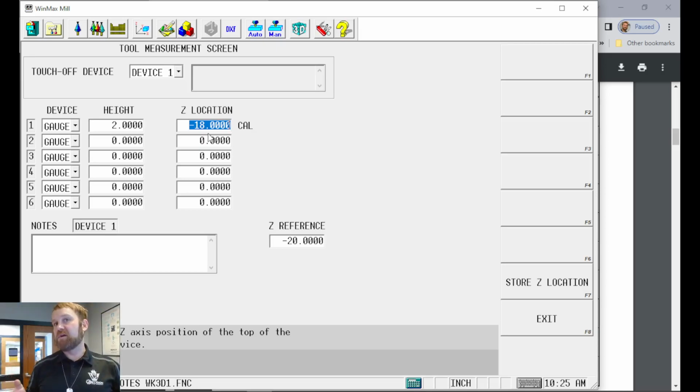Why do I like this better than negative tool lengths? Anybody have an idea? It's automatic. I don't have to do the extra math for the Z height. But what I like more than anything about using absolute tool length is, when I'm out there at the machine, I can pull my tape measure or my pocket scale out, and when I set a tool, I can hold it up and look across the tip of the tool, and visually see if it's stored correctly or where it should be.